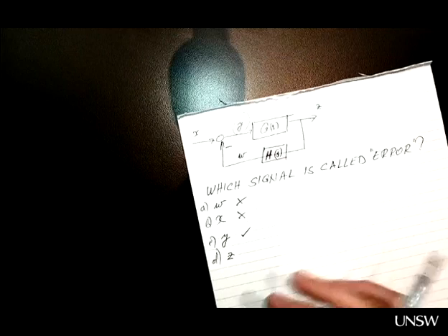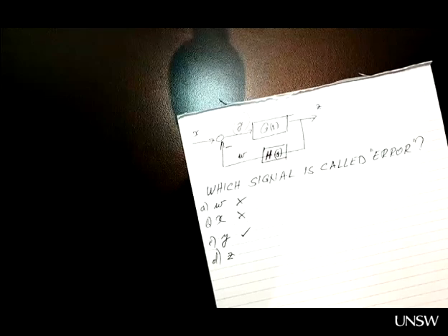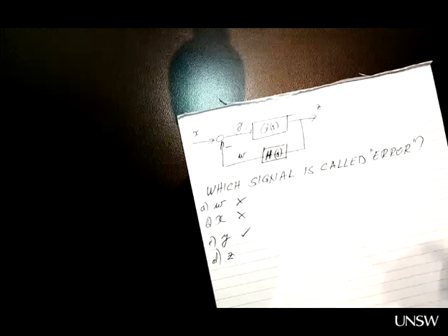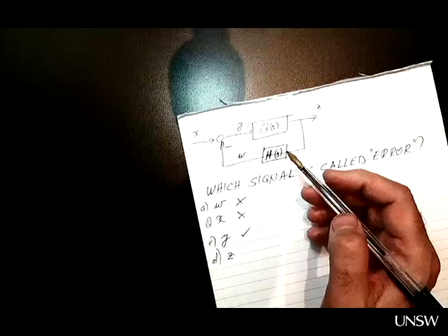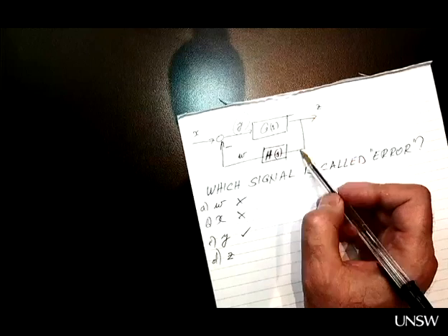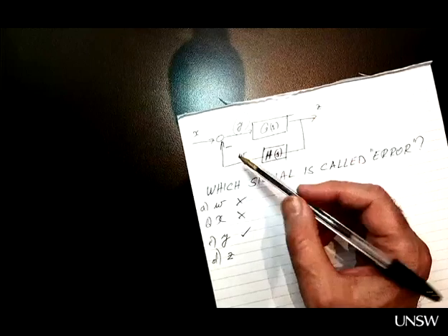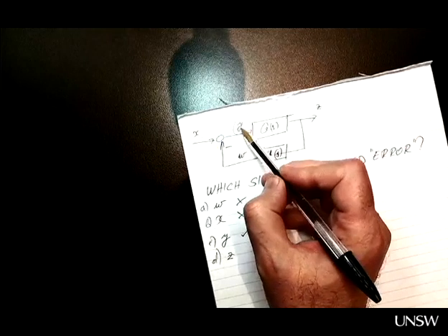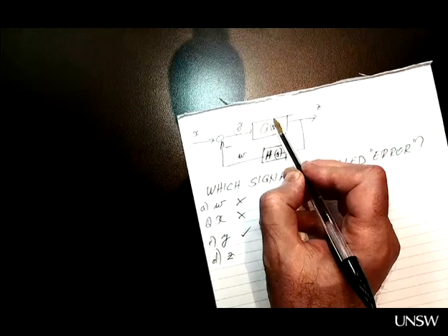Once again, temperature control system. When we start the air conditioning, we hope to achieve 20 degrees. Okay. If that's what we have, this plant, this system here, the air conditioning system, will work in a steady state regime, maintaining 20 degrees. If there is a difference, you know, if someone opens the door, so as a result of that, we have a difference, this error signal will drive the air conditioning up or down to increase or decrease the temperature here.